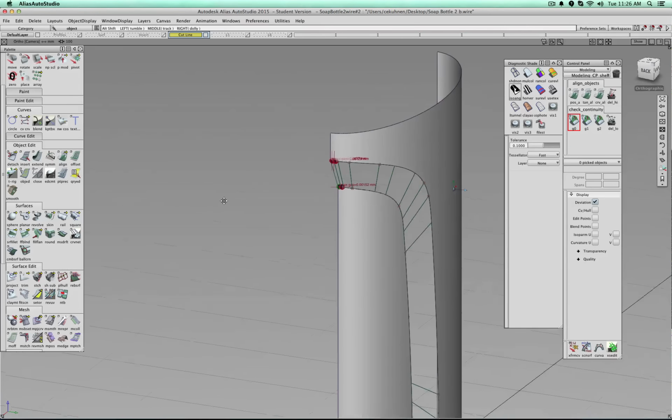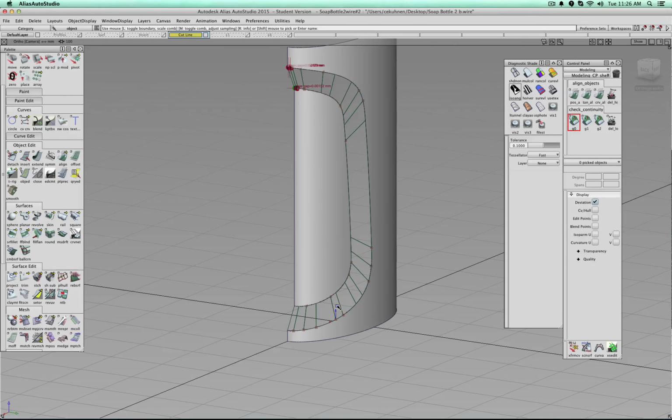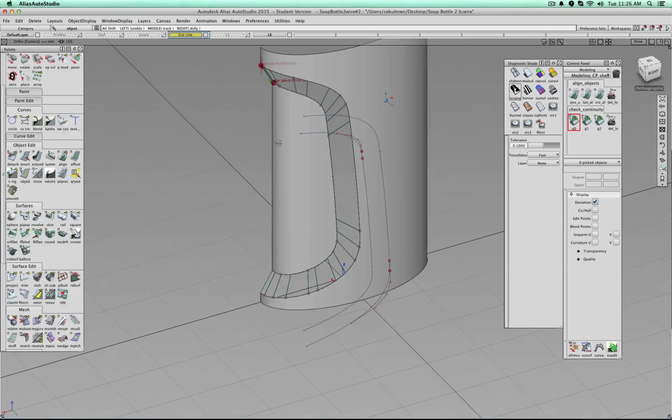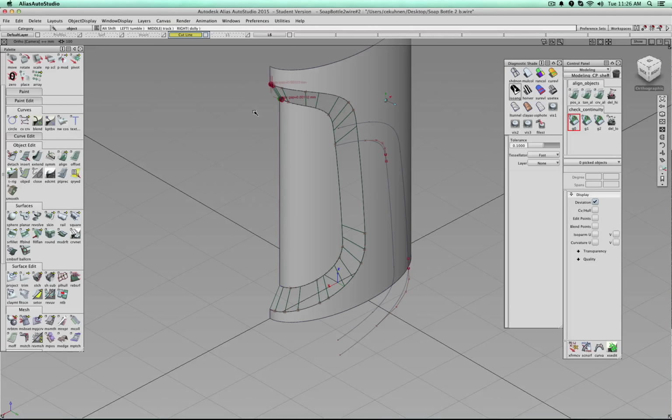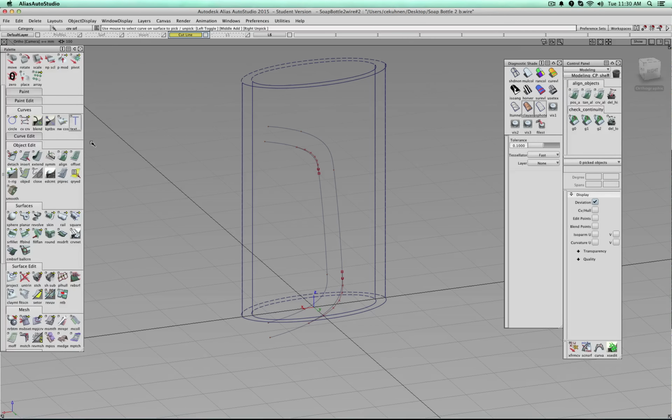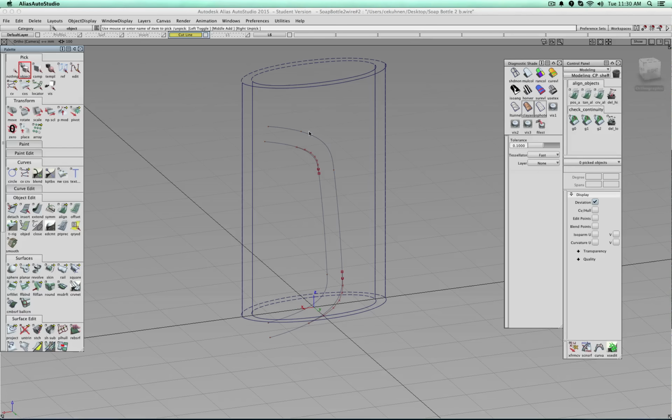Yeah, so, okay. At this point, maybe it might be simply better if I try to fix this. Maybe I could have solved this one too by recreating this blend curve, the last one, maybe with a higher degree, so I have more control points. So here I'm back, and let me click this one. You see I changed them all to a degree 7, so I have quite a sufficient amount of control